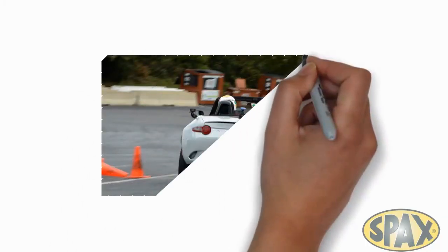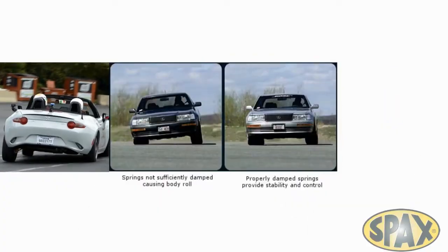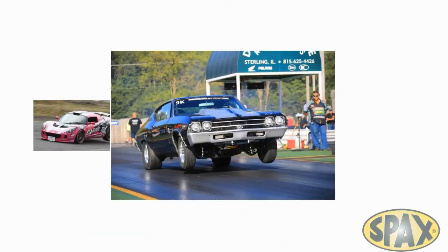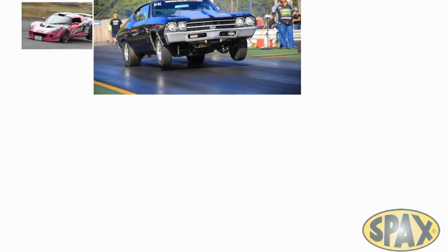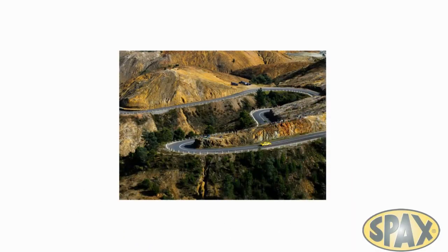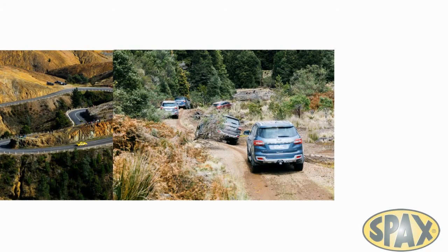As a car turns, springs will be compressed. On the other side, the springs will be extended. If the car springs are left to their own devices, then the constant transfer of energy will induce body roll, adversely affecting road holding, car control and driver comfort. Similarly, as a car brakes or accelerates, the front and back springs will be in motion. In a typical journey, constantly combining speeding up, slowing down, turning and hitting bumps and potholes in the road, dampers will be constantly working to offset the competing forces of momentum and help the driver keep good control of the vehicle.